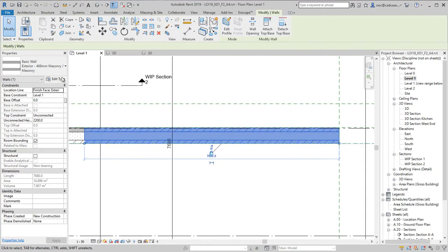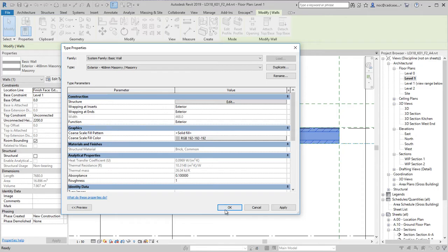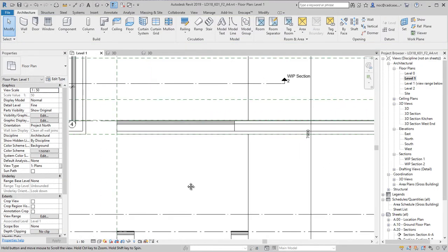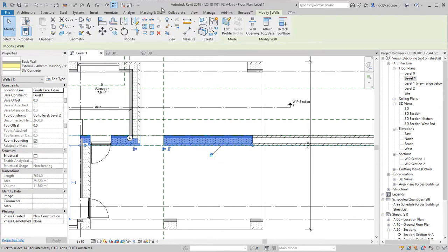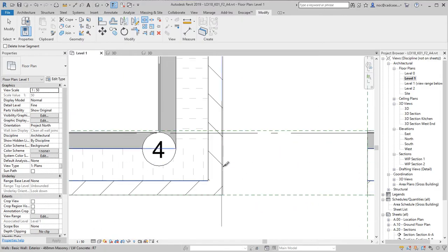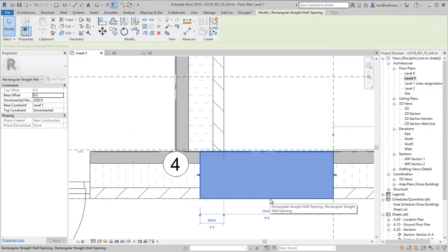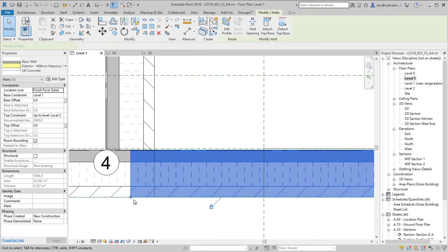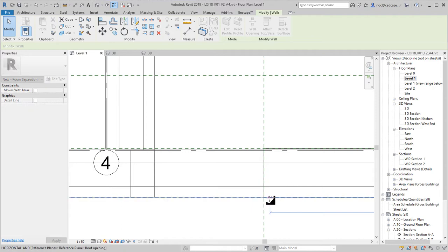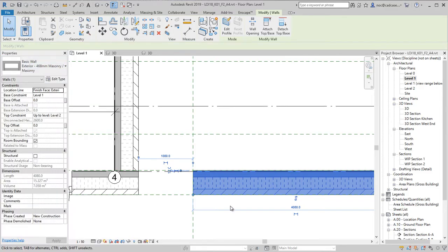And if we want to have the correct graphical expression, we can show that the brickwork will wrap around the ends. So I set the default wrapping to exterior at ends, and then it looks more correct. And since the model came from our outline proposal phase, where we modeled as fast and easy as we could, you'll see that since we modeled the walls with openings using edit profile, we have to split those walls so that we can divide this into the correct building parts.